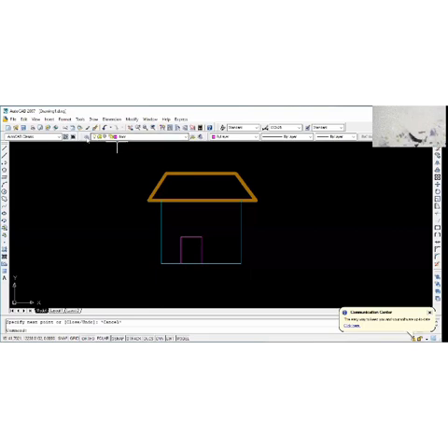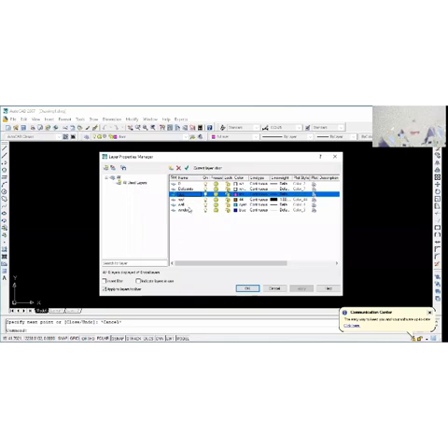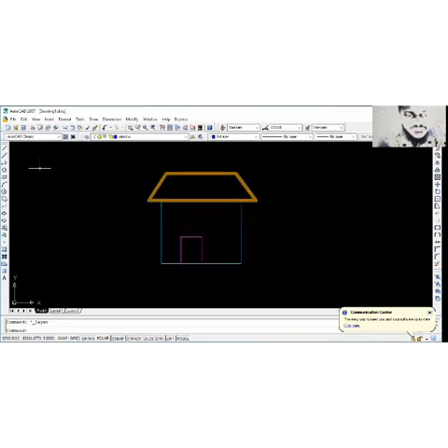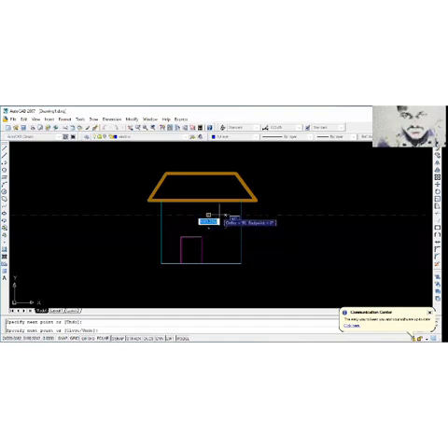So now let me come to layers properties toolbar again, left click. Now let me take my window. Let me set window as my set current layer. Left click on the set current and then okay. So now I come here, I take my line command, or I can just press L enter. Now I want to draw my window. I have this. My auto is on. I have this. So it's perfectly horizontal. It is perfectly vertical. I click here and then I click here, and that is my window.